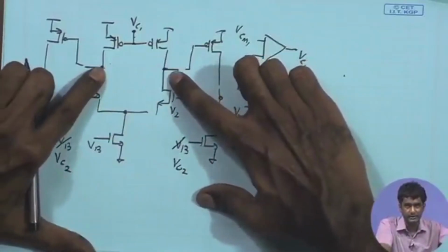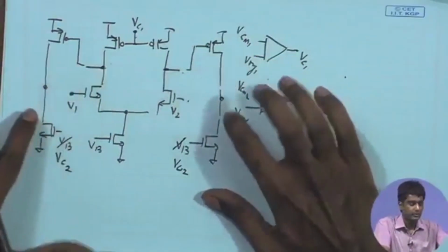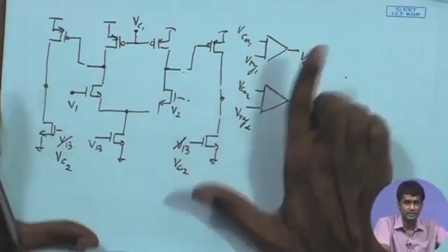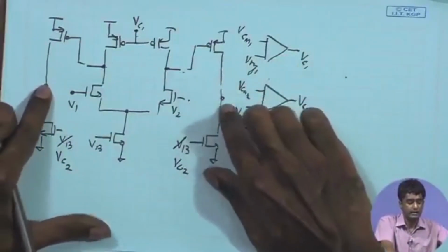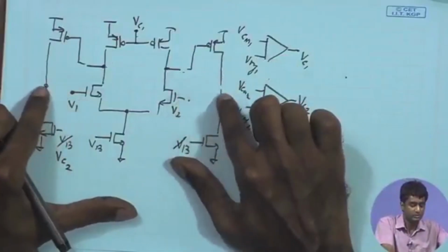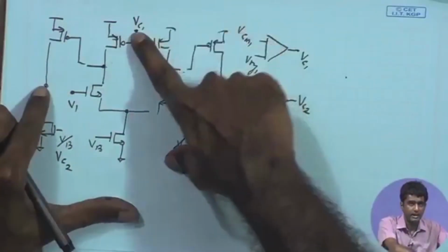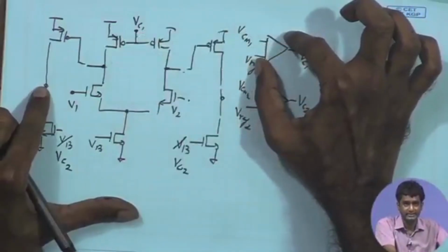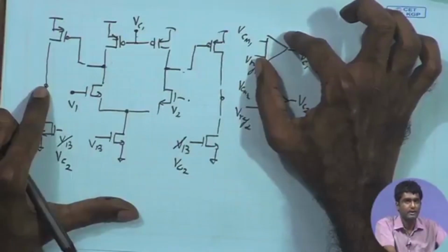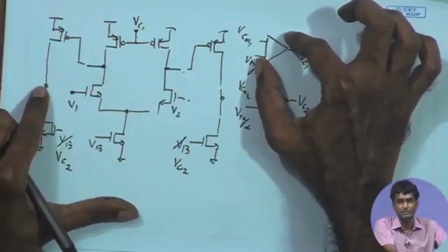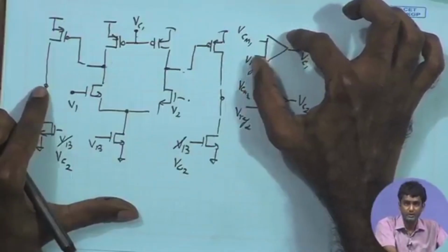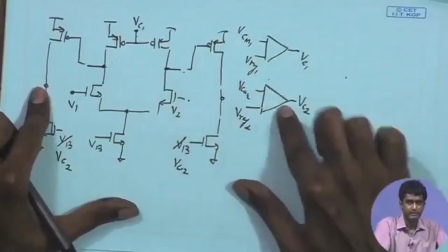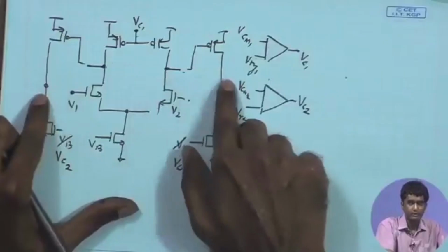So, in simulation exercises, we can see what happens if we rely on a single error amplifier and try to control the output DC point by just adjusting the VC1 with the help of a single error amplifier. That can be a more risky case, and it will be more clear when we look at the corresponding simulation example. It will be better to explain with that. So, in general, for more robust design, people prefer having separate common mode feedback for the two stages.